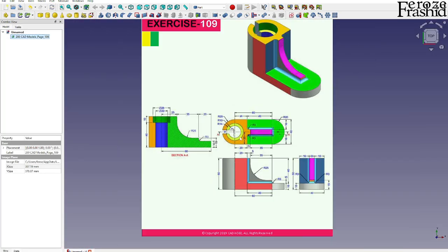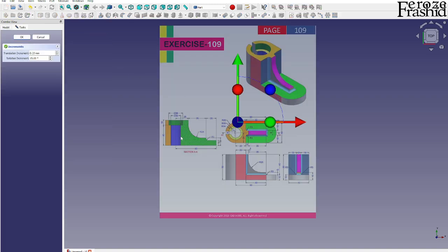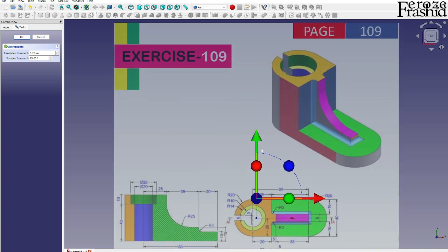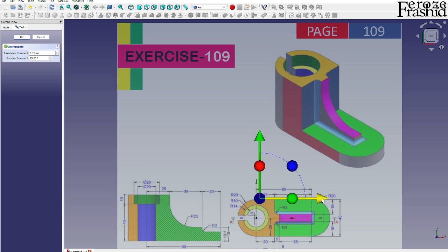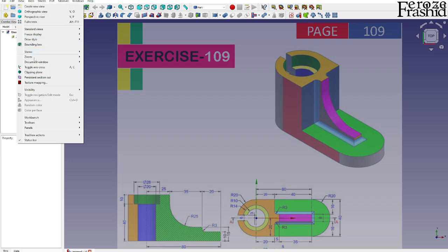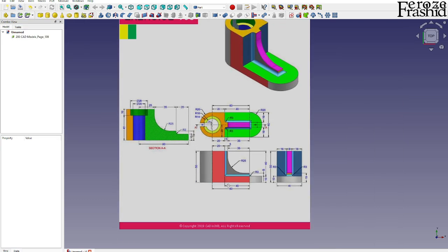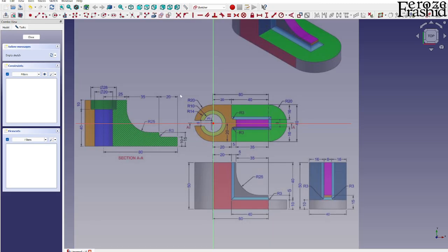So the image is in XY plane. Let's go ahead and adjust the location to the center of this slot, so one of the centers of this slot holes. And let's take the axis cross away. Now I want to start sketching on XY plane, and my first sketch would be a slot to be modified.